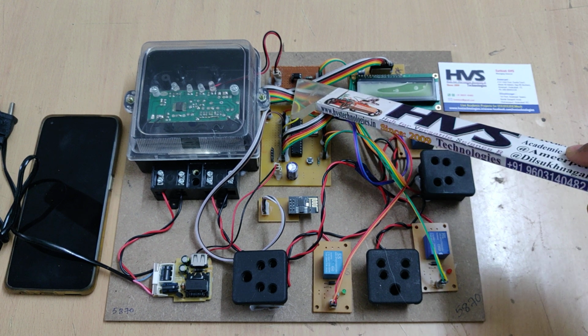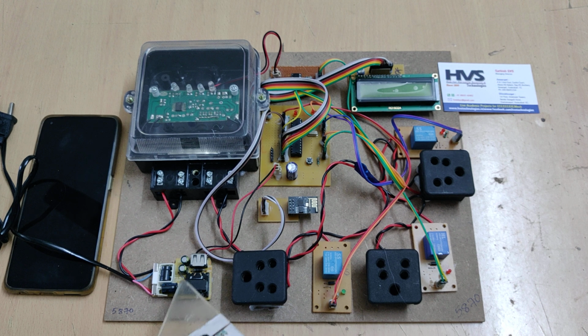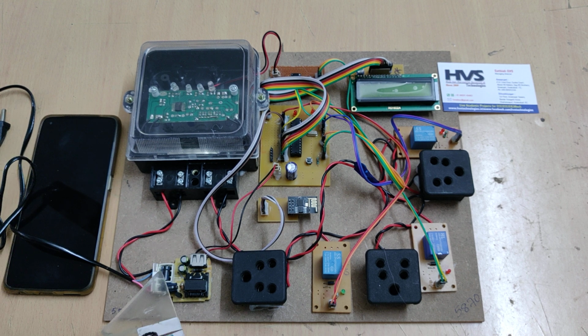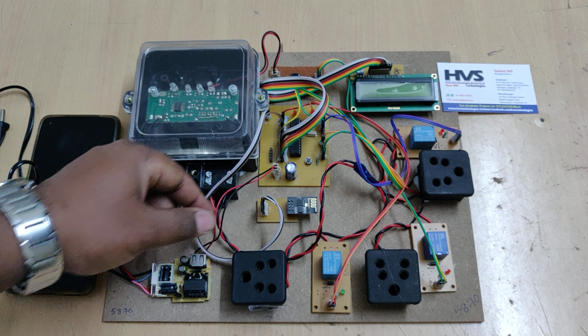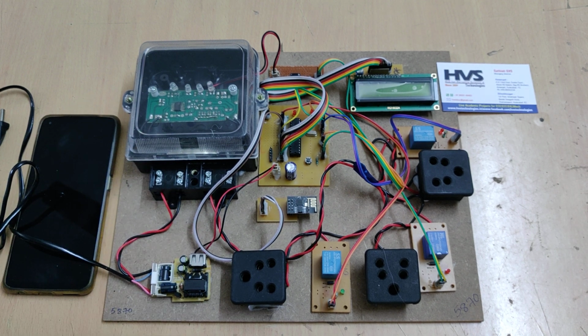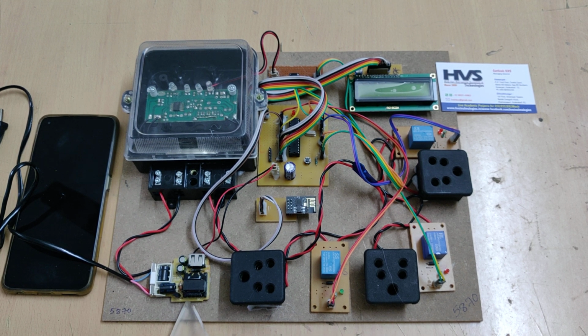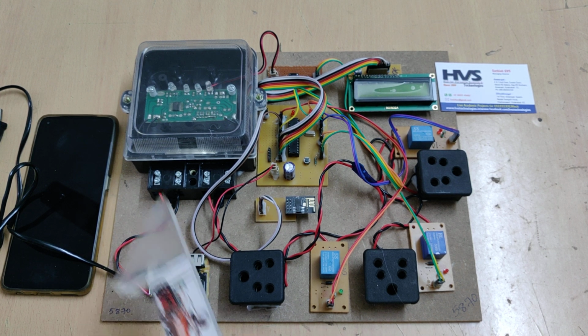That was connected at pin A4 of our microcontroller, and this is the regulated power supply board, which takes 230 volts AC input and provides 5 volts DC output directly to this microcontroller, as it has the stages of transformation, rectification, filtration and regulation. Transformation steps down the 230 volts AC to 12 volts AC, and rectification converts the AC to pulsating DC.